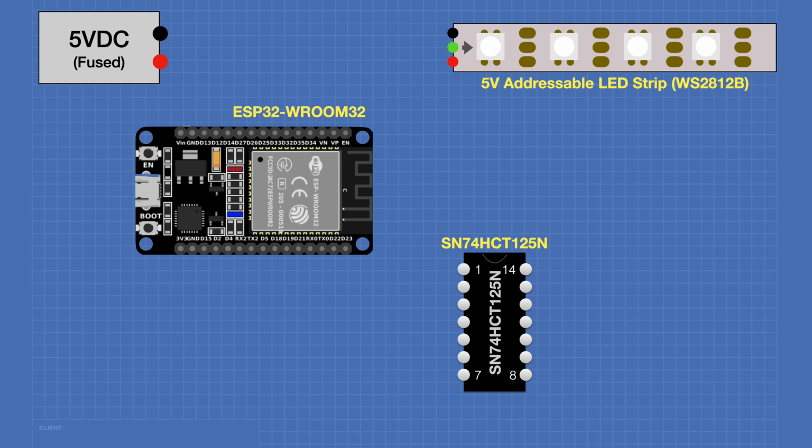You'll need a 5-volt power supply, and the supply should be fused. The rating of the fuse will depend upon the current draw on your LED strip. You'll require a 470 microfarad capacitor at pretty well any voltage, because we'll only be applying 3.3 volts to it, and a 100 nanofarad capacitor as well. We'll also need a 68 ohm resistor.